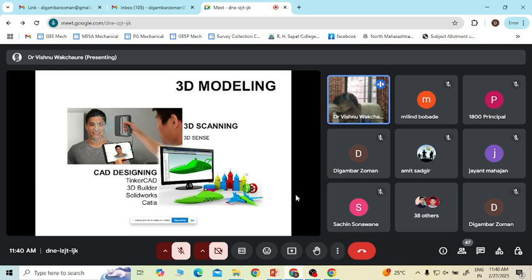That particular data of the 3D scanner will be taken and repaired if required, and you will get that particular model, and directly you can print that particular joint implant, right? I was referring to a knee joint. What happens is that every human being's physique is different, so you cannot have off-the-shelf knee joints and the like. For biocompatibility and compatibility with the dimensions of the bones and joints, you need customized joints. So we can have the 3D scan of the actual dimensions, get it printed to your required shape and size, which is more suitable for that particular implantation.